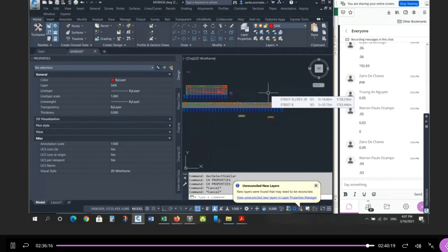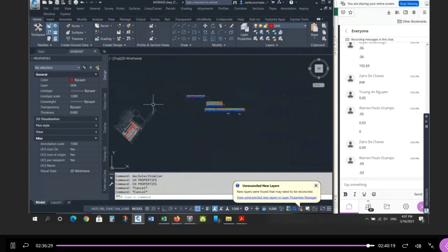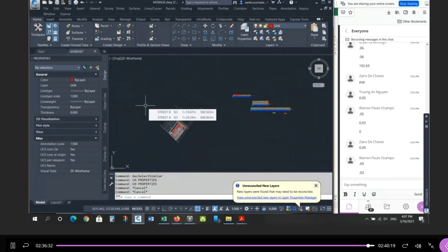Okay, I haven't done it yet, but I need to do my design sheet. I still have to prove the calculations, that all the pipe sizes have the capacity for the expected flows. Okay, so that's plenty of work for next week. The good news is you can do whatever you want. You can do the pipe drafting first, because those sizes and slopes aren't going to change, or you can do the spreadsheet first. Right? It's kind of chicken and egg. You do one or the other first, and then vice versa. The storm sewer is not so. You must do the storm sewer sheet first to get your sizes and slopes, and then you draw your solution. And we'll cover that next week.